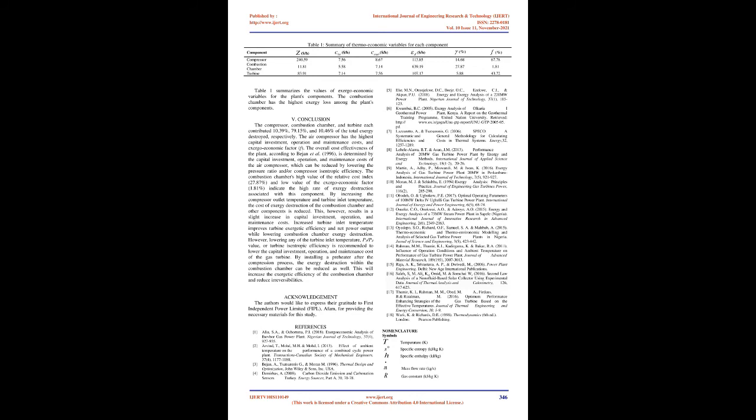As shown in Figure 8, the exergy performance coefficient decreases by 3.22% as the turbine's inlet temperature rises from 1319 K to 1337 K. The rate of entropy generation and irreversibilities increases as ambient temperature rises, resulting in a reduction in power output and, as a result, an increase in plant improvement potential. Figure 9 shows how plant improvement potential increases by 4.2% as ambient temperature rises from 300.8 K to 301 K.